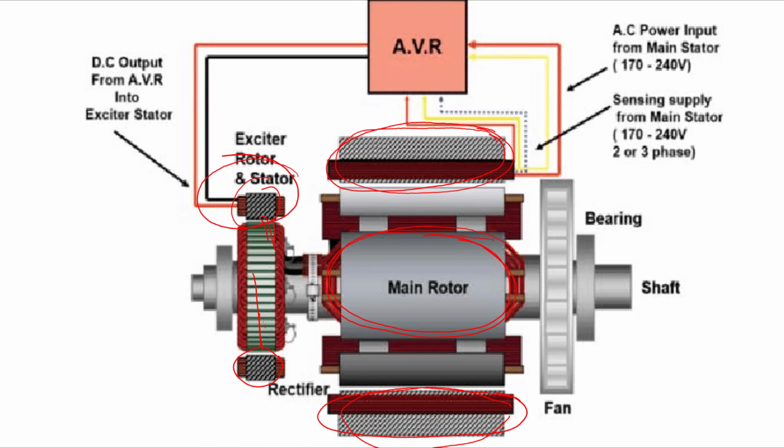There are varieties of arrangements you will study in your power system perhaps, but now we will not discuss. In order to design this exciter for the synchronous generator, there are varieties of arrangements. There is the pilot exciter, and sometimes it is called a static exciter. Sometimes it is excited through another DC generator which is placed on the same shaft, right? But the most recent one, as per the IEEE standard, is the static exciter. Through the static exciter, we excite the field of the generator, right?